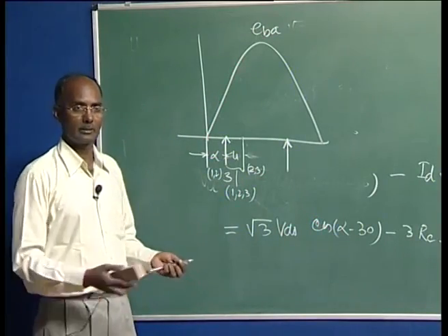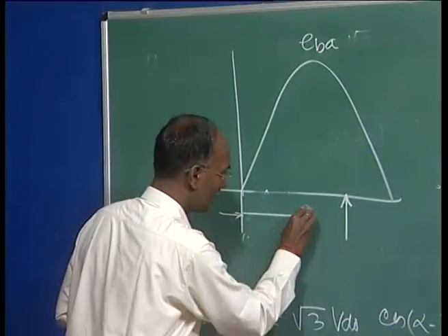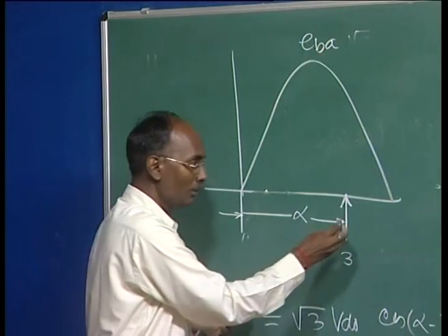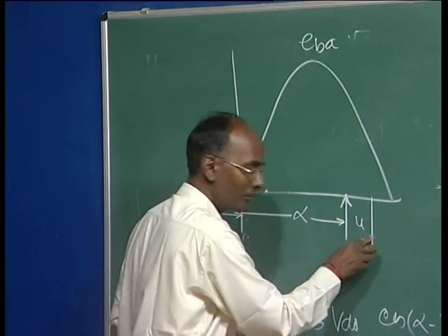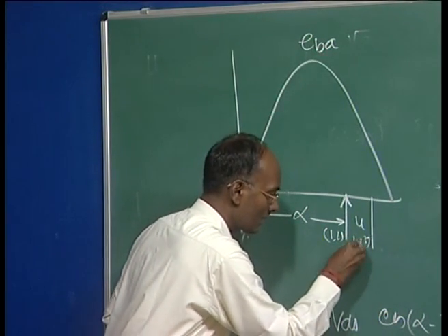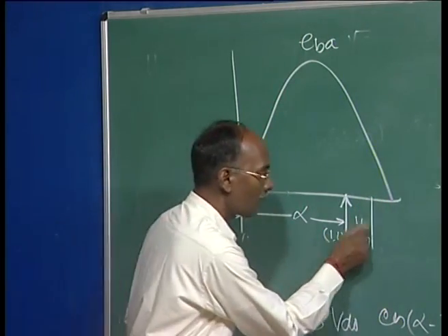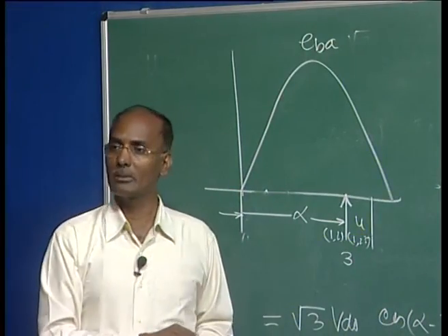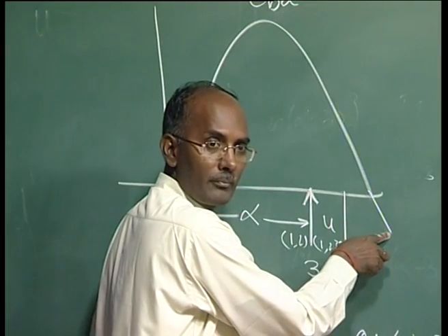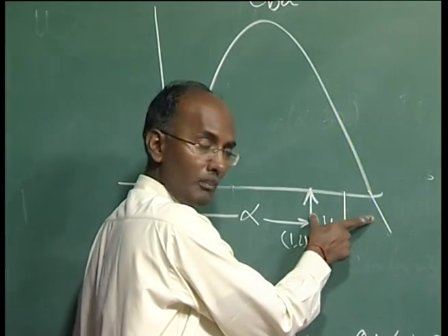But once you are firing here, that is the inverter case, where you are delaying your alpha, and your alpha is now more than this, then you are giving a pulse here. Now this will take your overlap angle u; again, 1 and 2 were conducting, and now 1, 2, 3 are conducting. Here we are giving some margin, because this may enlarge somehow and the commutation may not complete properly. So, now the voltage reversal is there. If the commutation is not completed in this period, your commutation is not complete.